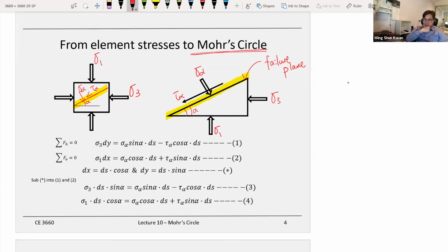And we can further define the dimensions of each length here. We define this length to be dy, and this length right here to be dx. And this length here, it's hard to draw, to be ds. So we know the stress and we know the area: the length times the dimension into the page, which can be a unit, 1. So we know the area and we know the stress, so we can calculate the force, because stress times area equals force, just like in statics.